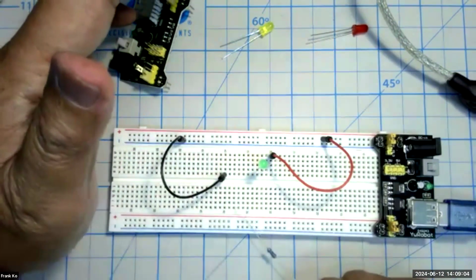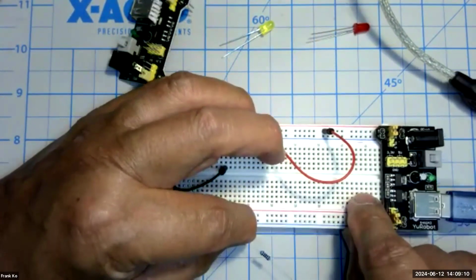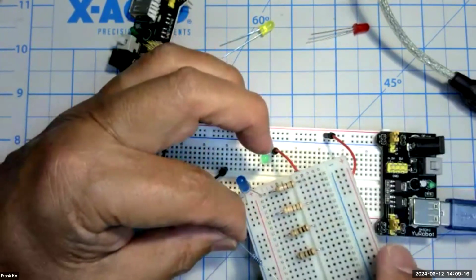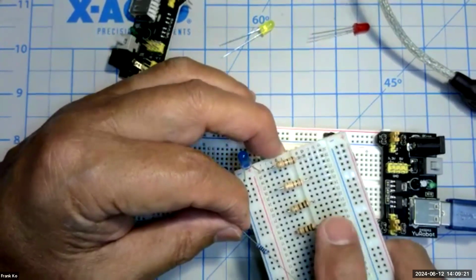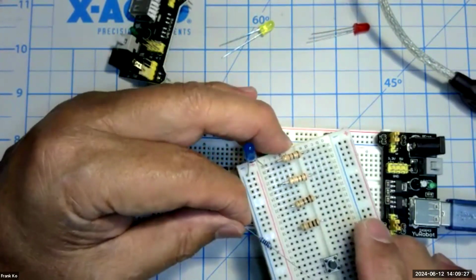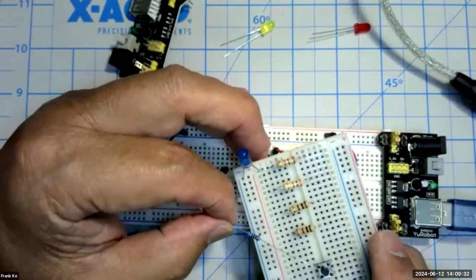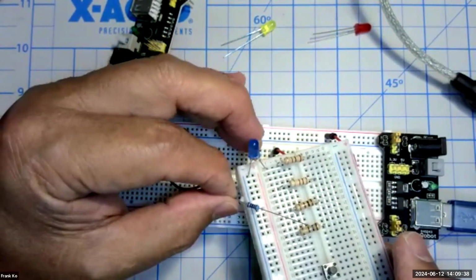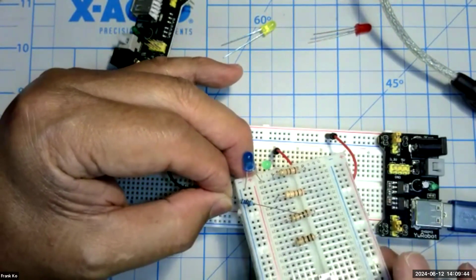And this is what we call a 1/8 watt resistor, meaning that it has to do with how much heat this guy will dissipate in comparison to physically larger resistors such as this, which can be 1/4 watt or 1/2 watt resistors, meaning they can dissipate quite a bit more heat. So the physical size of the carbon resistors that we're using is indicative of how much heat they can dissipate safely before they burn out. One of the things you'll notice is the wire of the resistors we're using is fairly thin. In comparison, the larger wattage resistors have much thicker, more stout wires.